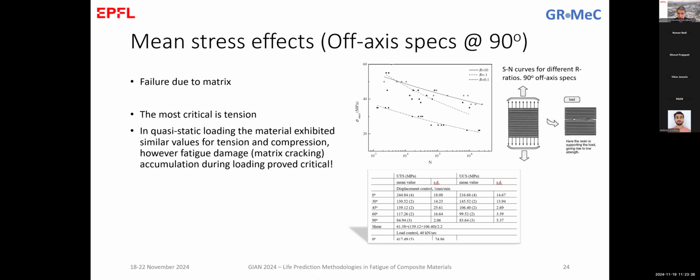And there is also, for fatigue of composites, a lot of discussion between groups. There are groups, especially from Denmark and the Netherlands, that even prefer for unidirectional composite laminates to use a kind of dog bone specimens instead of the rectangular specimens that we are using, because they believe that the stress concentration that is relieved by these dog bone specimens is improving the behavior.